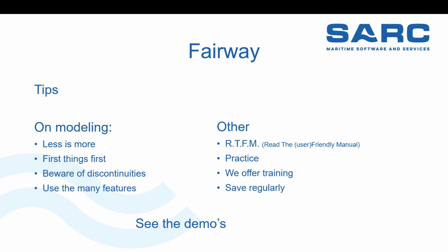Then, first things first. So what do you do first? Your contour should be one of the first things. Your deck line, a chine somewhere. The basic stuff, really, a flat side, a flat bottom, the knuckles in the right position, the tangent dependencies. I will show you that later on, but yeah, don't start manipulating your, I don't know, your anchor pocket before you have done your hull.